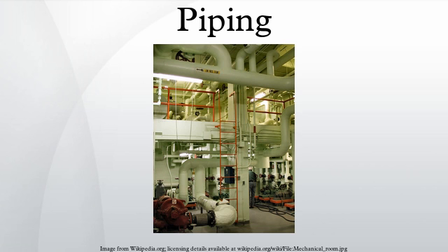Engineering subfields. Generally, industrial piping engineering has three major subfields: piping material, piping design, stress analysis. Stress analysis, process piping and power piping are typically checked by pipe stress engineers to verify that the routing, nozzle loads, hangers, and supports are properly placed and selected such that allowable pipe stress is not exceeded under different loads such as sustained loads, operating loads, pressure testing loads, etc., as stipulated by the ASME B31, EN 13480 or any other applicable codes and standards.